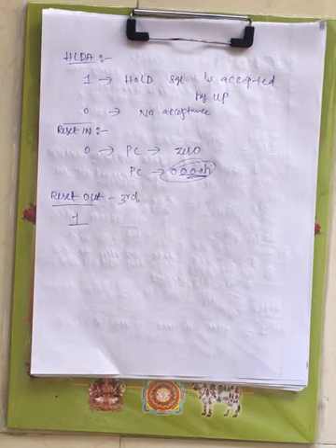Now what will the program counter do? It will store the address of the next instruction. When reset in bar is 0, whatever address is stored in the program counter will get vanished. That is for active low, since it is bar.